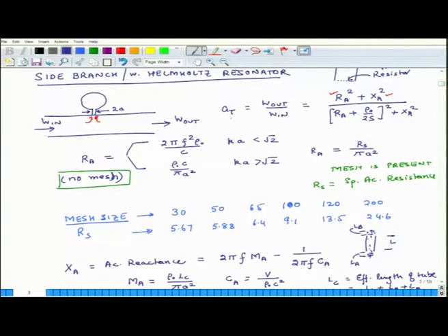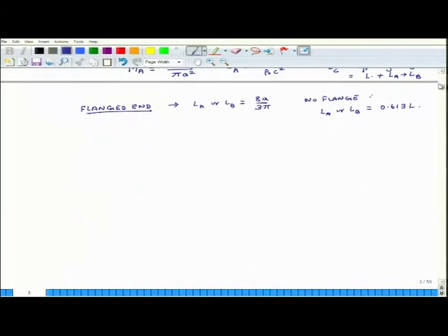So, with this we can calculate how much sound power is getting out of the pipe. If this ratio is 1, then my muffler is not at all effective. If this ratio is very small, close to 0, then my muffler is effective. So, we had also defined that transmission loss is equal to 10 log of 1 over alpha.